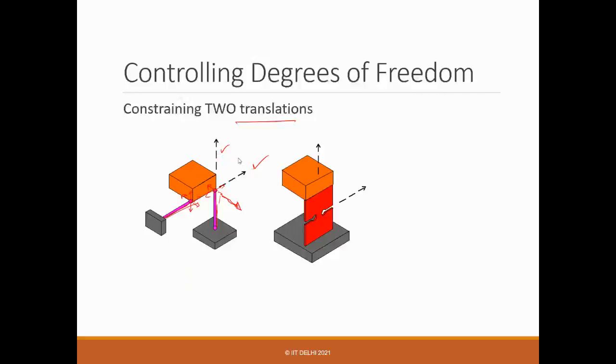The flexure embodiment will be this leaf spring with the holes. So what happens here? Suppose we have this leaf spring. What we say is that it is constrained along this direction and along this direction, right? Rotation is also constrained, but the moment we take this, we make two holes and then a slit, right?